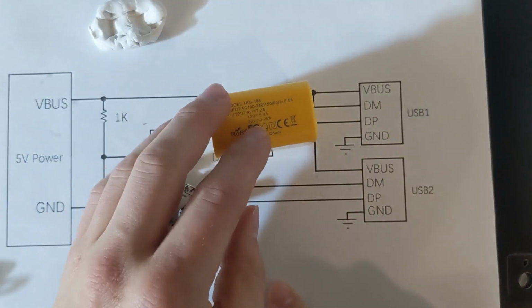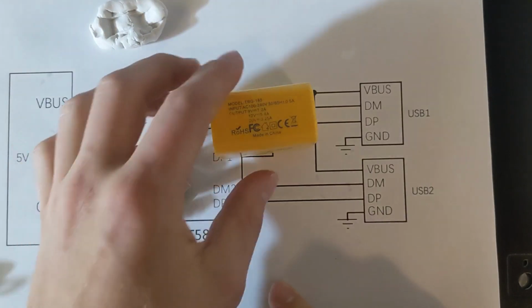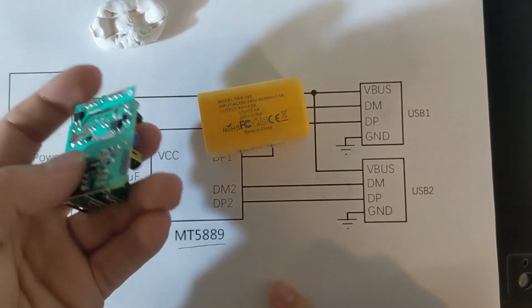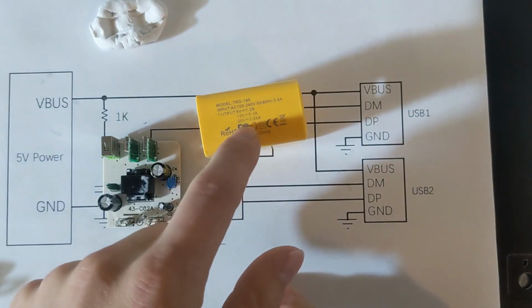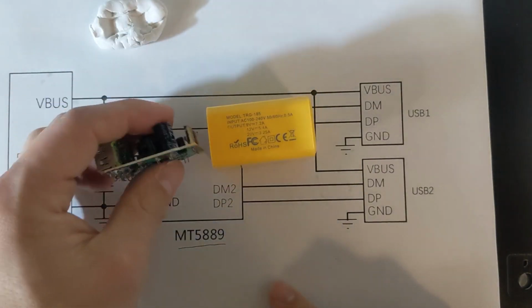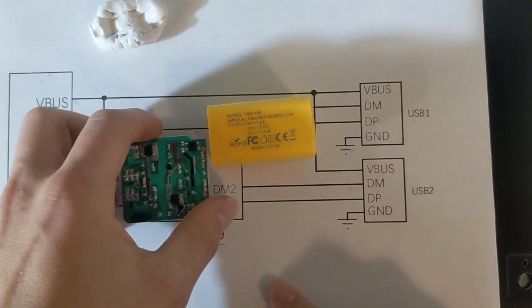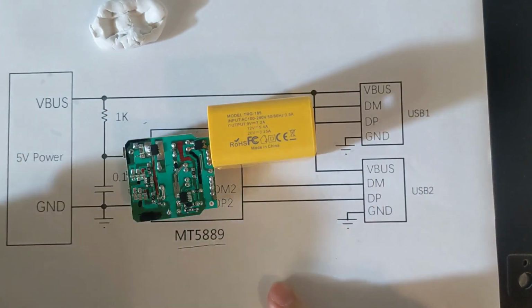it's quite a bit of a lie, because they say 9 volts, 7.2 amps. Now, I wouldn't have known that unless I had used my little adapter and plugged it in and looked at the CC lines and found out there was no communication going. If there's no communication and I couldn't get the 20 volts out, I quickly realized this was a fake. It's a counterfeit. It's junk. But, I mean, it still will charge a phone, just way slower. And so if you have issues with your phones, you got to find out what's going on.